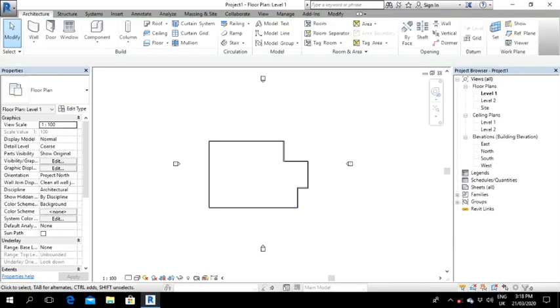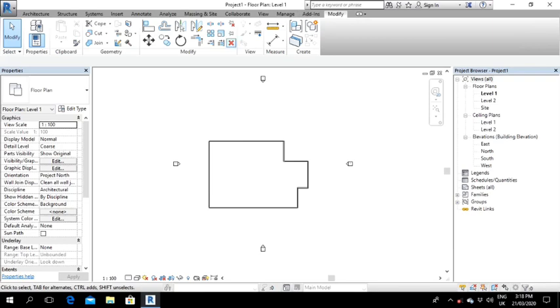Now say we have this kind of drawing right now. I want this particular curve to be represented here. That means we want this line to be extended without having to clean this whole thing afresh. So all we have to do is go to modify, click on align. Now select this line, select the same line. See, it aligns immediately. So that's how align works on Revit.